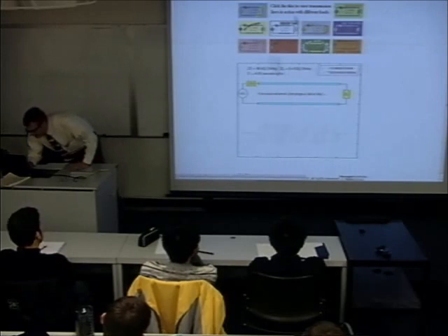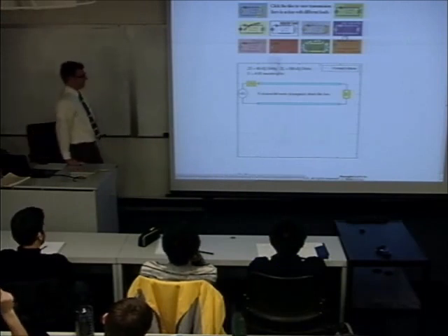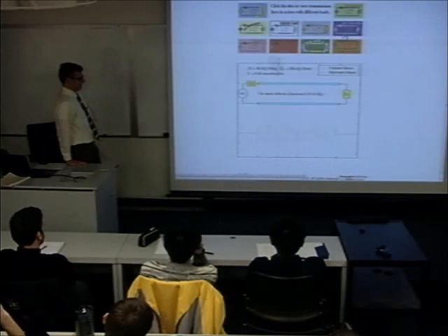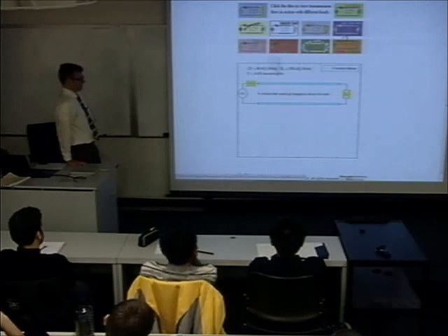Let's see. See a big mismatch. This is a 250 ohm load. You see the reflection coefficient produces a backward propagating wave that's maybe 2/3 the value. And there we get a nice big voltage standing wave ratio. Not quite infinity, but 5 or 6 probably. That's what it visually looks like.